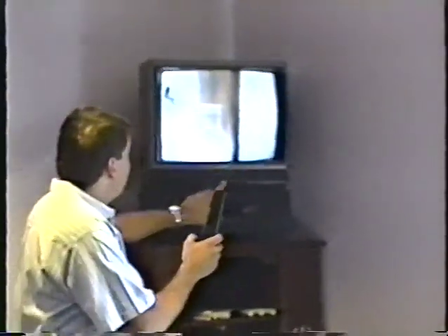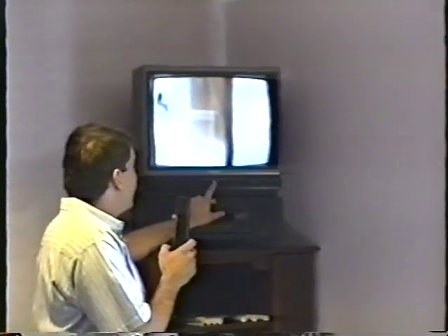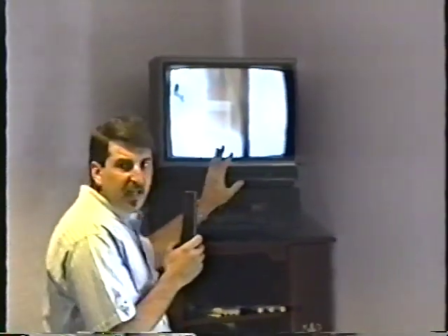In a regular television, the channel changer part of a television is fairly complicated. It's what we call RF, or radio frequency circuits. And RF circuits are really critical and really hard to work on. You really cannot use a meter to fix them for the most part. You have to have an oscilloscope. You even have to have a special probe on your oscilloscope called a demodulator probe.